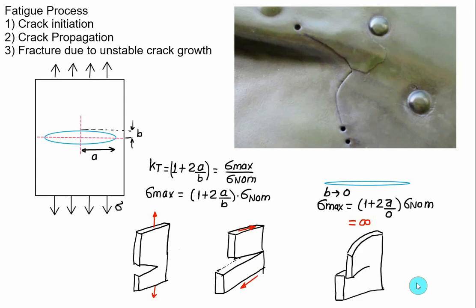The third mode of crack propagation is again due to shear, but this one is out of the plane. Out of the plane means that one force will act in this way, and a second force will act parallel to it but out of the plane. This one is in-plane and this one is tension. This phenomenon is more common in the fatigue failure.